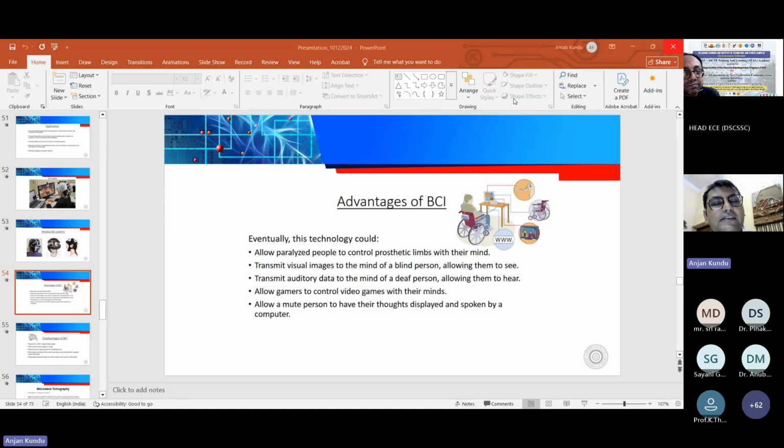The outcome of our research work is that if we design the capsule at 2.45 gigahertz or at 5.2 gigahertz, by nature the capsule will be smaller in size. More importantly, the communication range will be a few meters. If I have a mobile with me, 2.45 gigahertz or 5.25 gigahertz is the Bluetooth or Wi-Fi frequency, so it is readily available in the mobile.